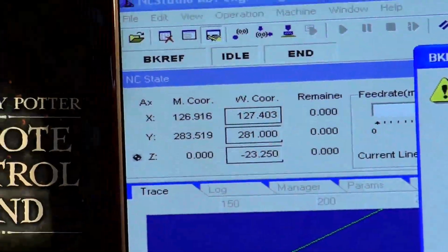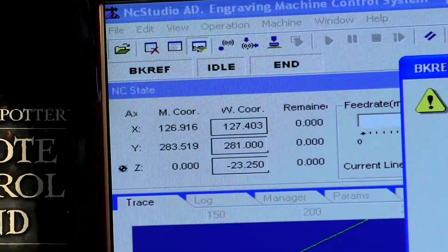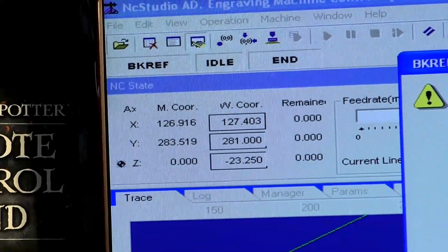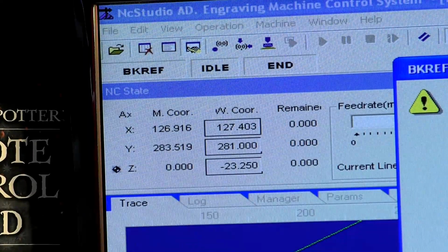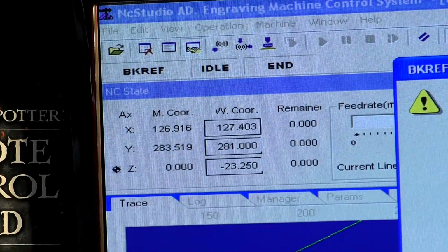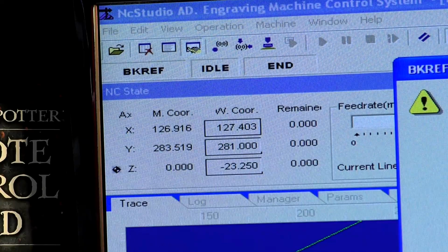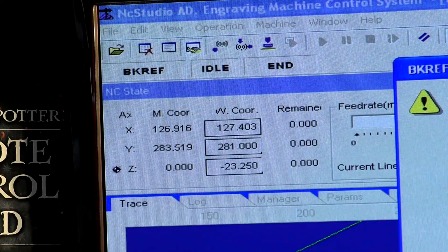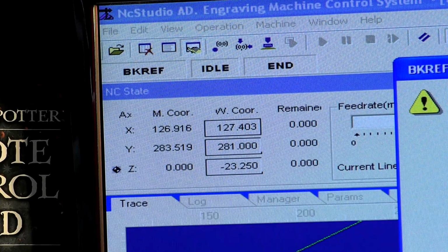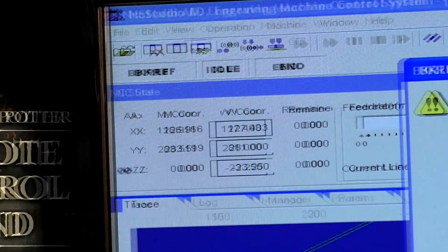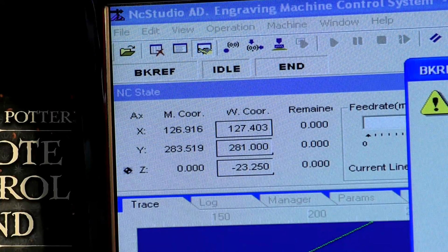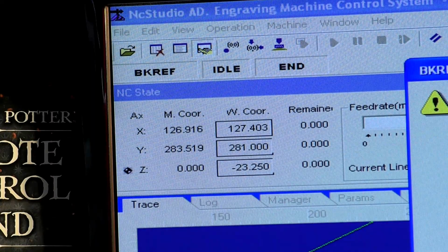And you can see there's that target I was talking about, and the machine coordinates have zeroed. The numbers next to it are the work coordinates, or set in the G54. So this time I'll leave it up there so you can see the numbers coming down for the X.